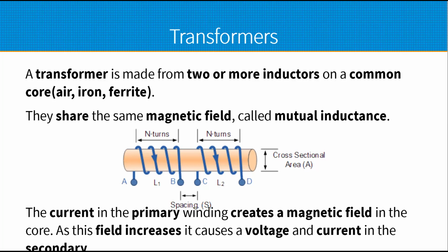So what was that? Only 5 seconds. Yeah, 5 seconds. I don't know. It's because the copper pipe is acting like a one-turn coil that's shorted together. As that magnetic field moves through that coil, it is creating a current that's creating an opposing magnetic field that's trying to prevent the magnet from falling, which is what happens in a transformer, basically. And if there were no losses, the magnet would be stationary.